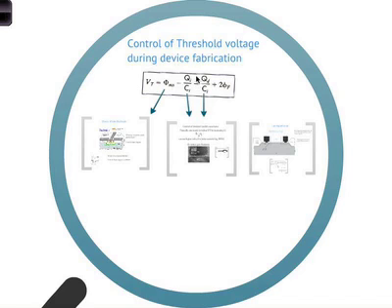This term is the charges inside the insulator, Qi. So that's the impurities within the, or interface charges, it's actually, sorry, that's the inversion charges, my mistake. I haven't included the interface charges, the oxide charges yet. So ignore what I just said. Qi is the inversion charges, just the inversion layer. Pretty straightforward. Qi over Ci is the voltage required to create the inversion layer.